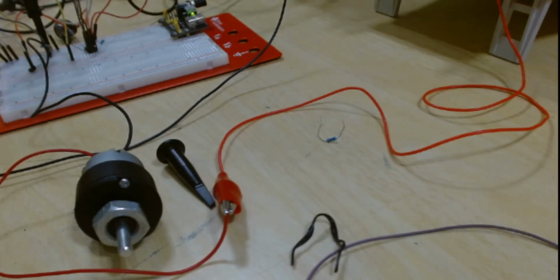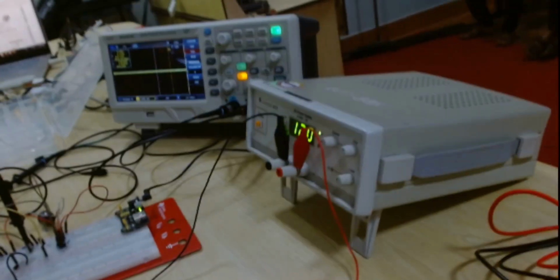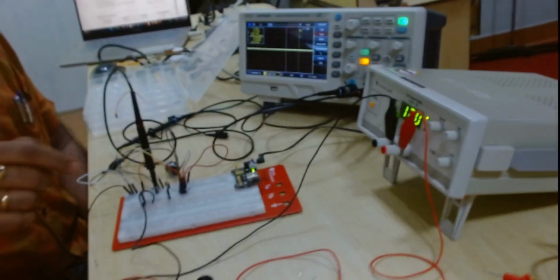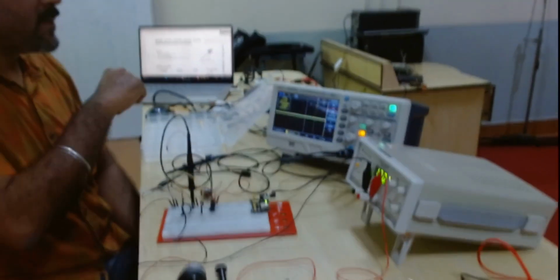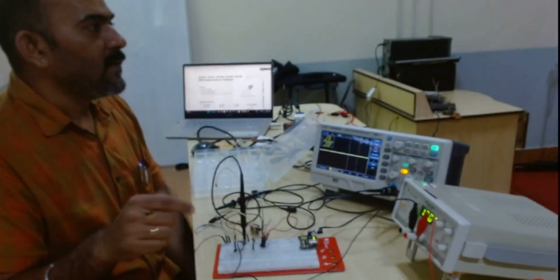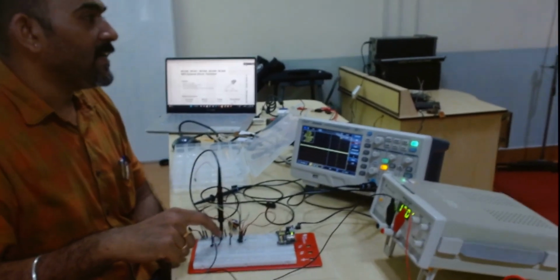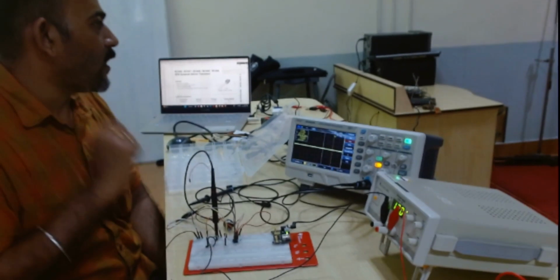You are getting the waveform, but the circuit is not working as intended. So this is a fault now. Here we now have to see each and every point what is happening, whether the voltage is there, still it is not coming. Then we have to debug what is the reason for the current not coming. That is the base drive. So we have to now change the resistor. So this resistance is the culprit here for this not working.